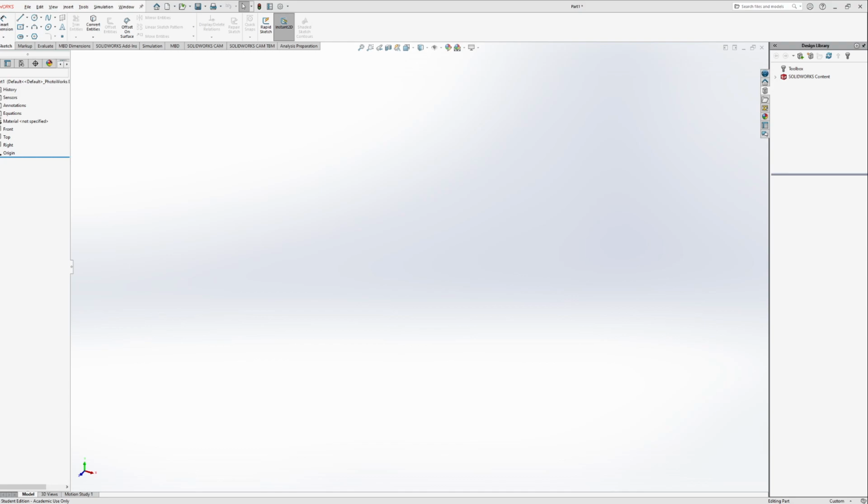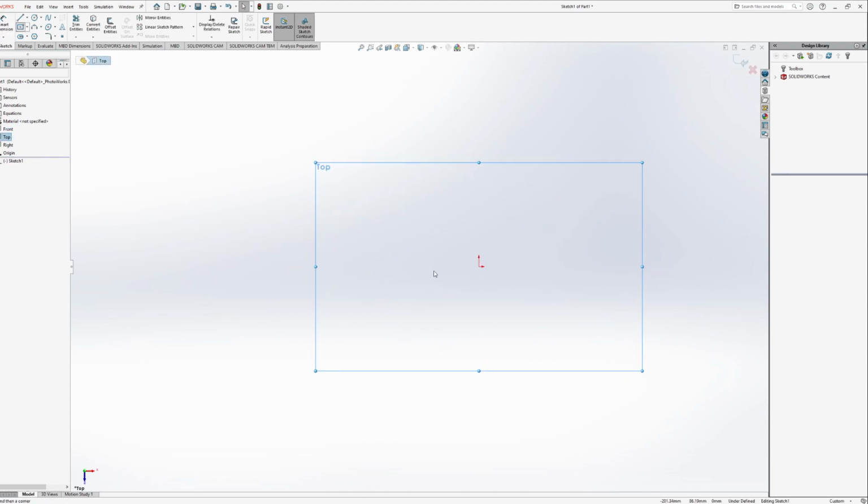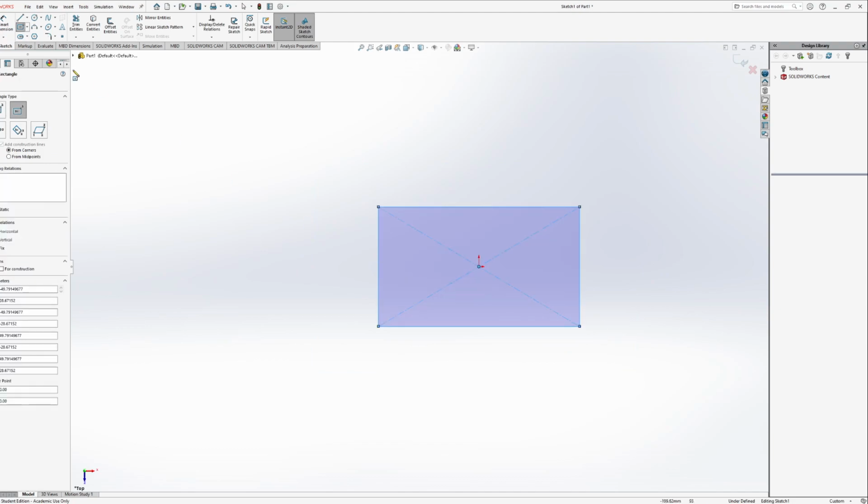I'm seeing that we have two rectangular prisms that could just be stacked on top of one another. So that might be the first approach that we want to take. It's also telling us that we have a material of AISI 304, units are in inches, and we're given a mass. So let's just start building this right now. I'm going to take the top plane and I'll just make that base.